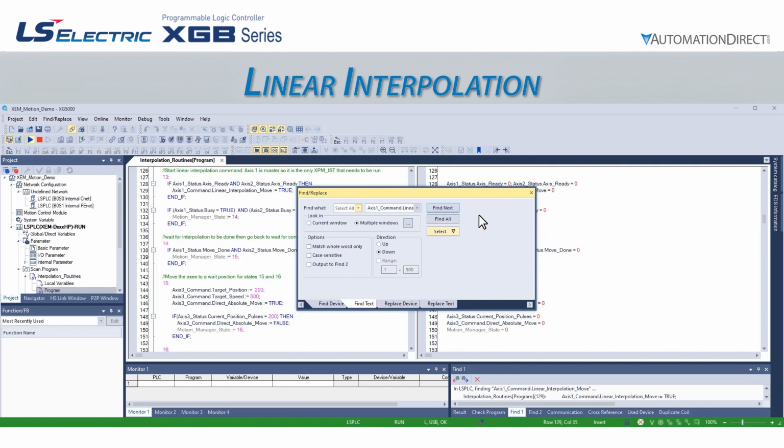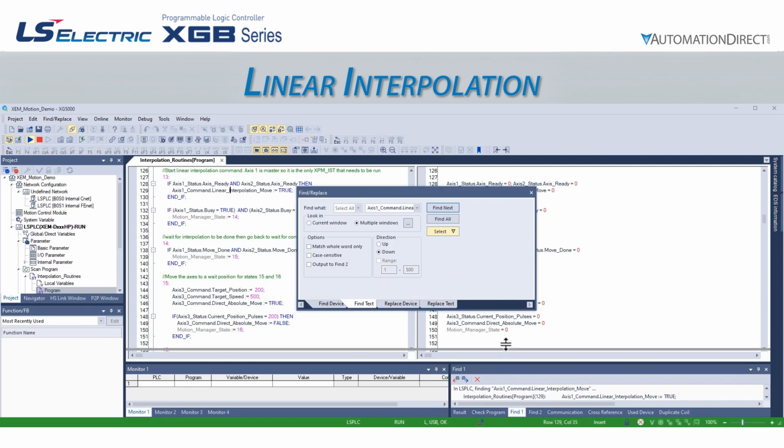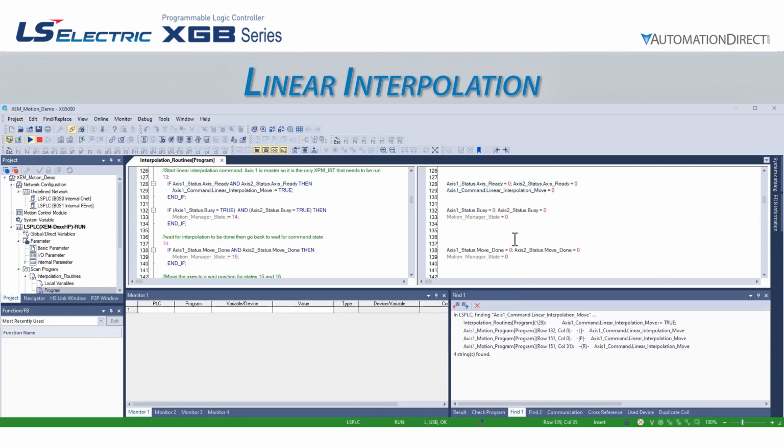It doesn't appear that anything happened, but if we look at the information window in the lower right corner of the screen, we see that the Find One tab has automatically been selected. Let's expand that window upwards, and here we see the results of our search. We see that Axis1Command.LinearInterpolationMove is used in 4 places. The first one is the spot in the interpolation routines program that we already looked at. The next 3 are all in the Axis 1 motion program, so let's take a look at them.